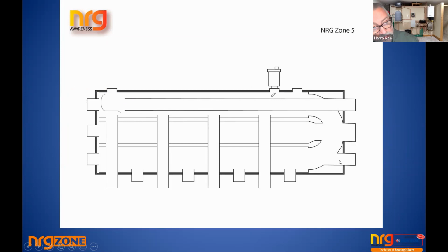In fact, what some people don't know is you can take the flow in here and take the return over here. You could actually take the flow in here and take the return here. You can take a flow into any chamber into the top, and so even a flow could come in here. You could put, say, for example, a heat pump in here, and maybe an oil boiler in here, but you're still reaching the chamber. So there's no definite rule. And the beauty of it is that it can suit your pipework.